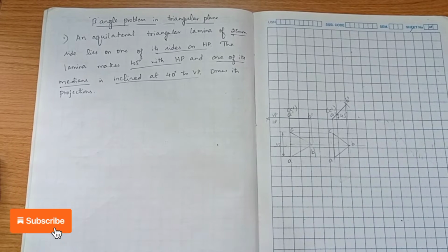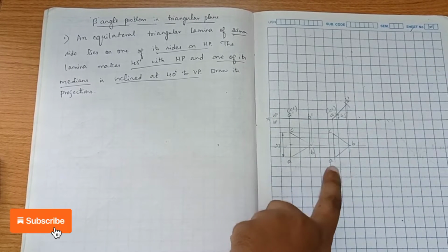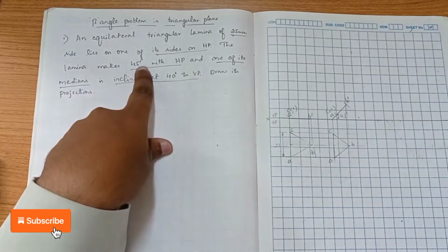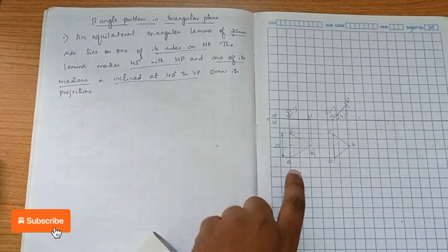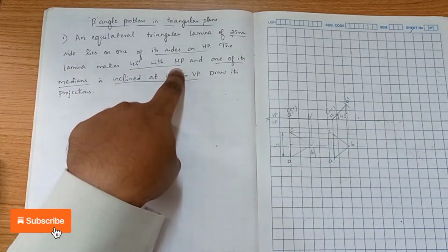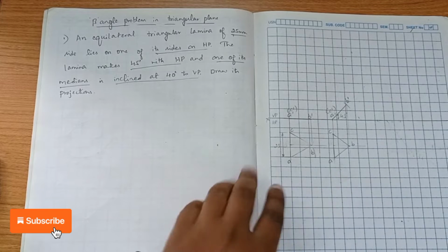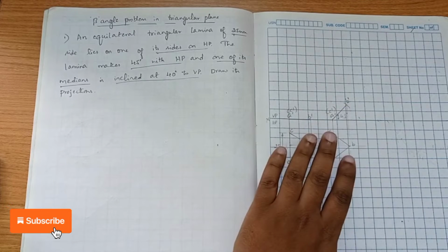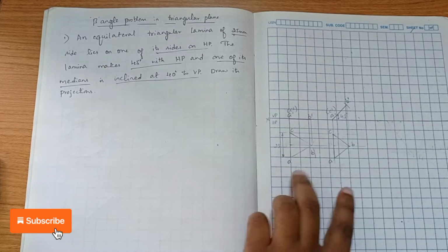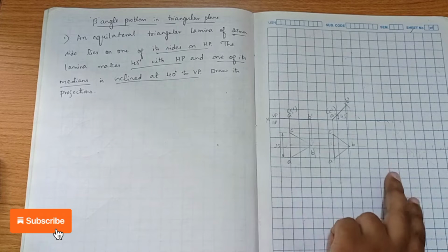In a beta angle problem, the first two positions remain the same. That's why I've drawn the first two positions here. You can see an equilateral triangular lamina of side 25 lies with one of its sides on HP, so we have constructed the first position, top and front view. Next, the lamina makes 45 degrees with HP, so the 45 degree inclination is also shown here. The only change with respect to a normal type of problem is in the third position; the first two positions remain the same. Now we have to construct the third position.